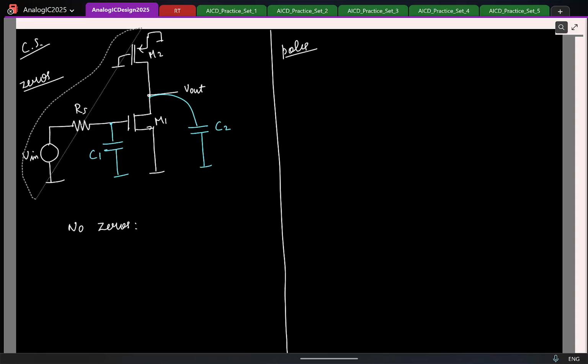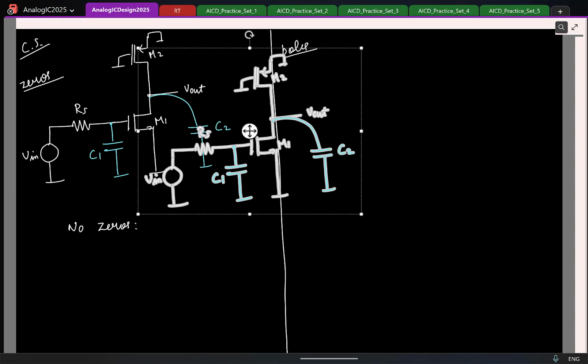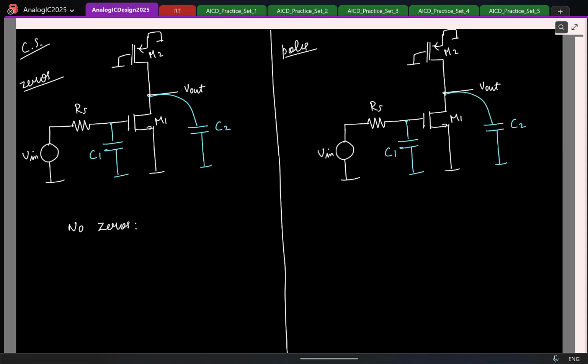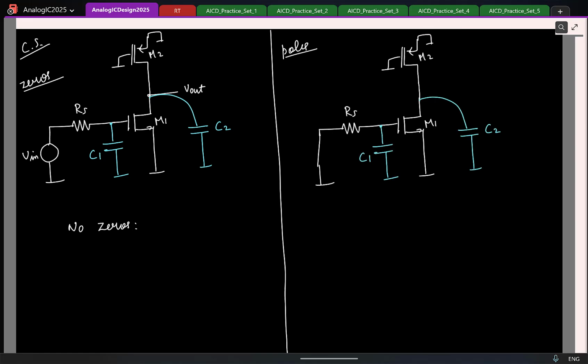Let's now look at the poles. So again, for pole locations, the input is irrelevant. So I'll short the input. So this is what I'll have. So how many poles do I have here? 2 poles. I can initialize both capacitor voltages independently without any contradiction. Now tell me, if these two capacitors have a second order system, once again, I can write the pole as 1 by R times C. Under what conditions? If they are uncoupled. So let's check if it's uncoupled.